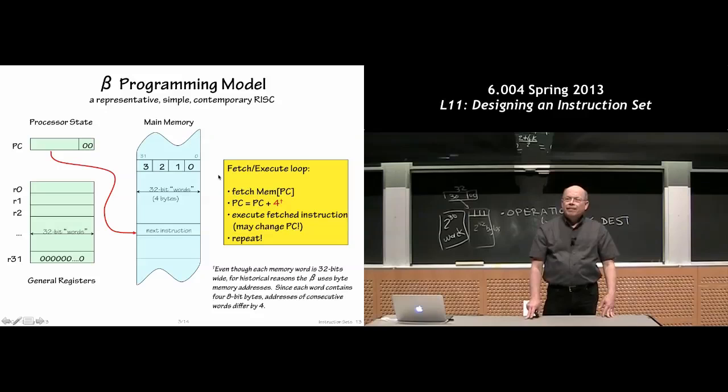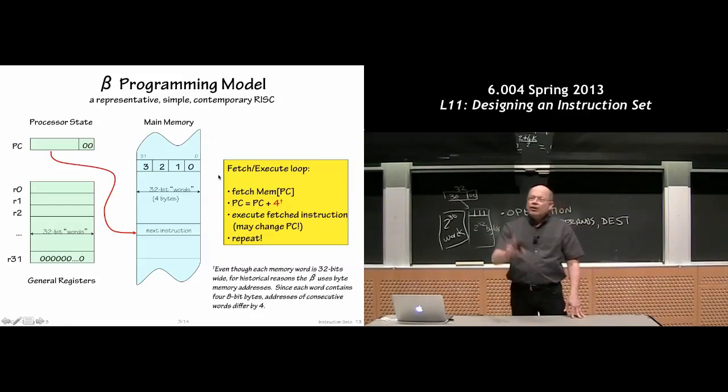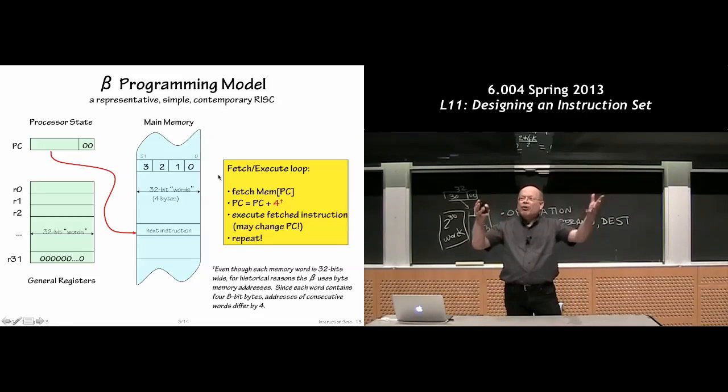Yes? So the processor has 32 registers. Yes. Each of which can hold 1 word. Yes. Each word has 4 bytes. Well, I'm with you up to there, and what you said is exactly true. But for most of our purposes, you just forget about bytes. We'll not spend a lot of time talking about bytes. Each word is 32 bits. The values are treated like 32-bit values. You manipulate them as 32 bits at a time, and we go from there.